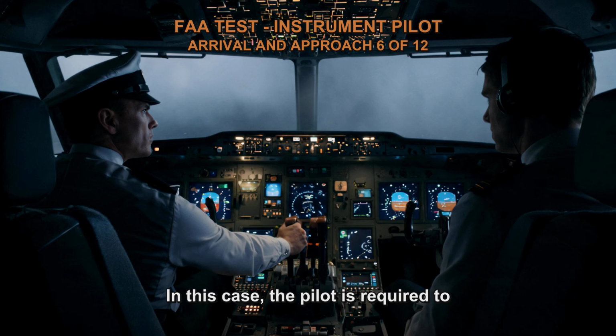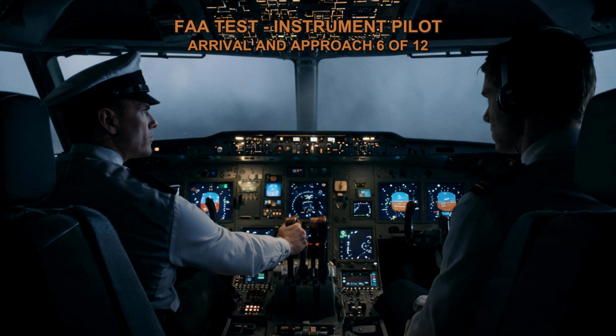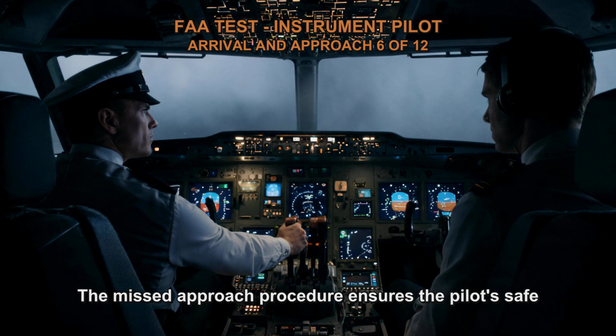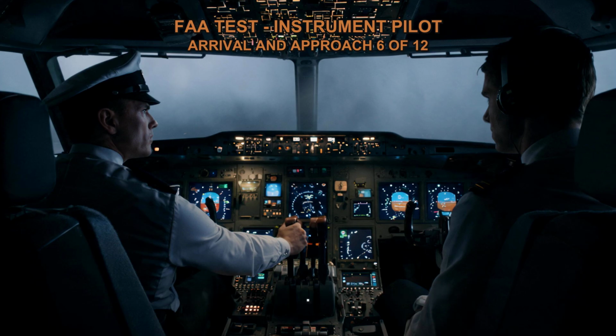In this case, the pilot is required to immediately execute the missed approach procedure as specified in the approach plate. The missed approach procedure ensures the pilot's safe climb away from the runway environment and provides a standard procedure to follow in case the landing cannot be safely executed.